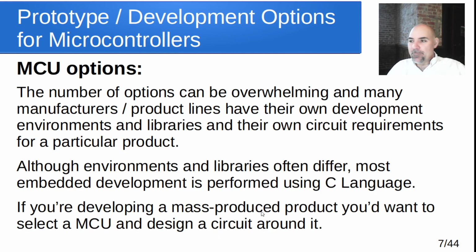Okay, now the number of options that we have there can sometimes be overwhelming. And different manufacturers have different product lines, different product families, their own development environments, their own libraries, their own circuit requirements. So sometimes when you pick a microcontroller that seems perfectly suited for the task, you also have to evaluate what are the tools like, how easy is it for me to set this up? Are the tools free and open source? Do I have to buy some kind of tool chain in order to use this thing?